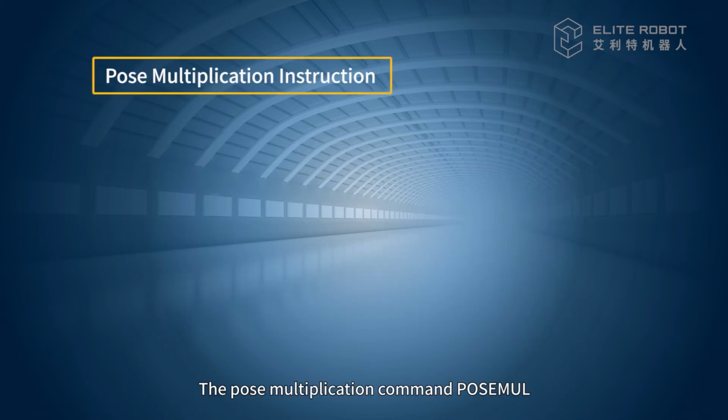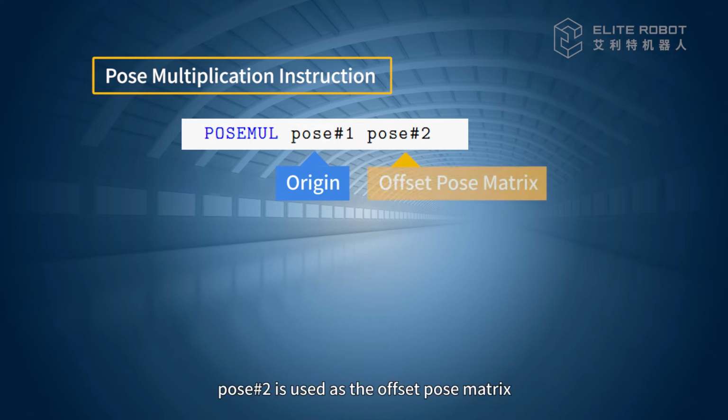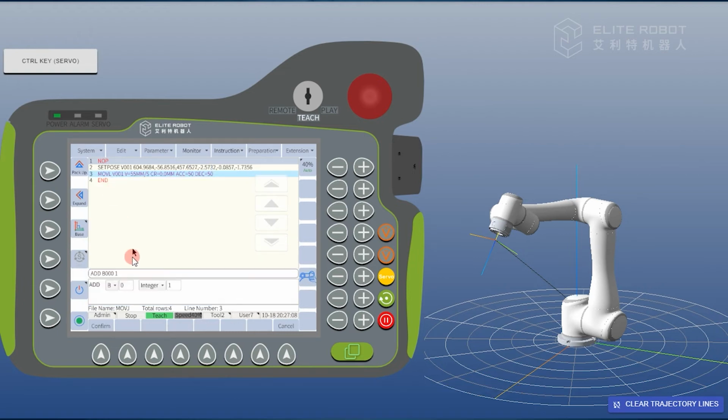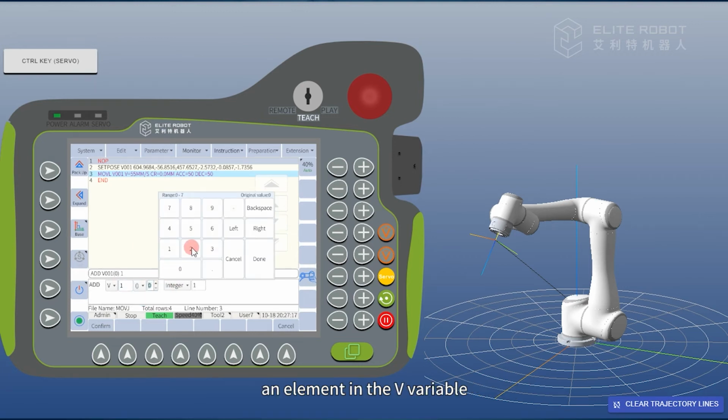The pose multiplication command posemul. Pose number 1 is used as the origin. Pose number 2 is used as the offset pose matrix. After the offset calculation is completed, the data stored in pose number 1 will be replaced with the result. Please consider the RPY of pose number 1 when using this command for offsetting purposes. Since MoveL supports v-variable operations, the position can be adjusted by offsetting an element with the v-variable.